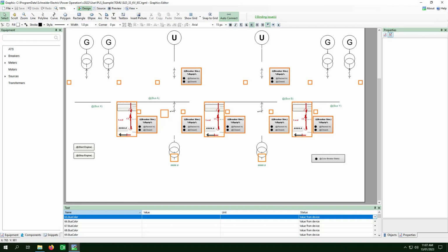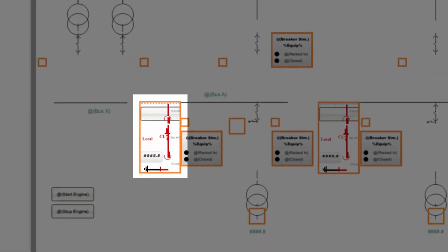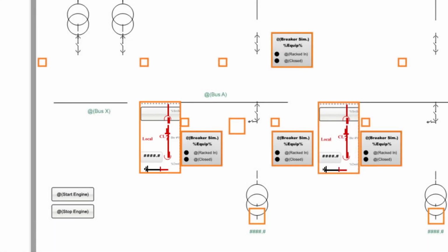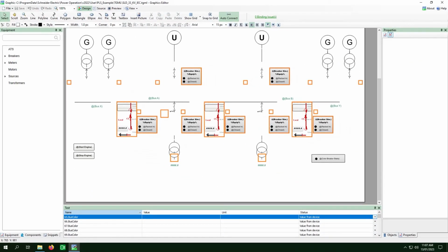If the checkbox to generate missing objects is used, a basic component that does not exist in the new graphics editor is generated as a visual indication, with placeholders on the page to demonstrate the objects that could not find a mapping component in the new graphics editor. This allows engineers to review the migration and create those components that do not exist to adjust the new graphics.